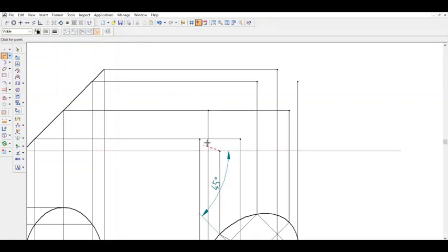Just go from one point to another point. Select 3 points. Right click. Then from one point, two, three. If you want, you can go for four as well. Just make sure that the curve should be somewhat between the limits. So that is your answer for the final particular question.